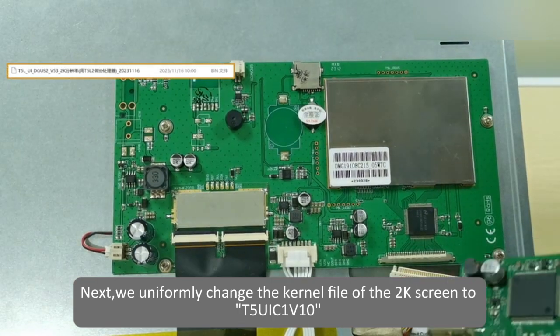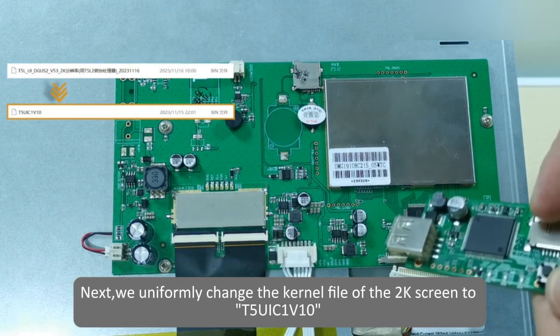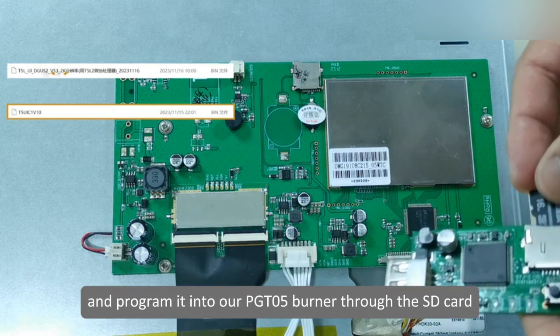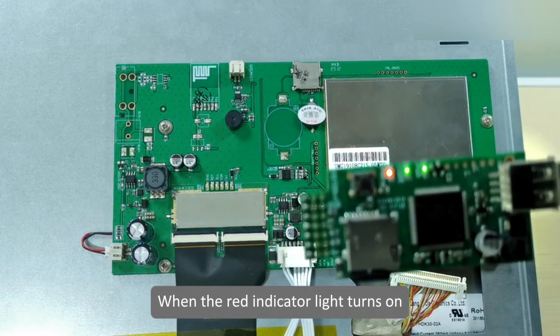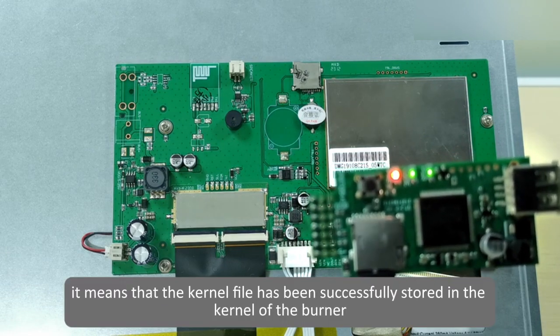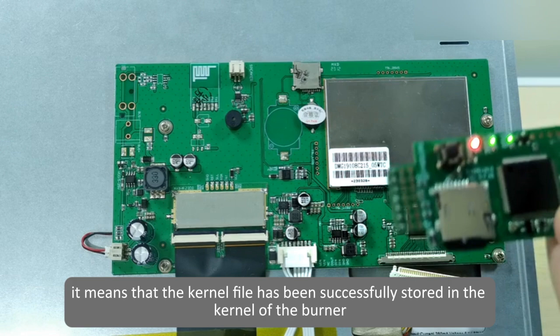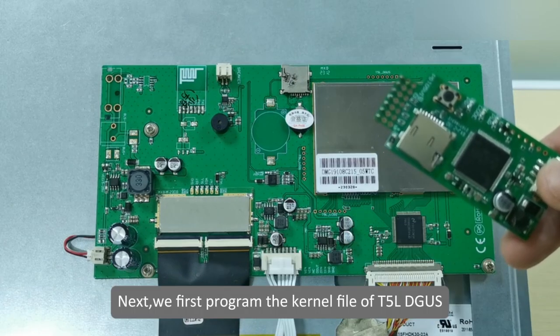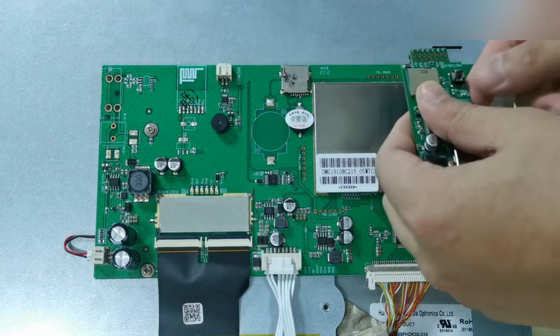Next, we uniformly change the kernel file of the 2K screen to T5UIC1v10 and program it into our PGT05 burner through the SD card. When the red indicator light turns on, it means that the kernel file has been successfully stored in the kernel of the burner. Next, we first program the kernel file of T5LD.